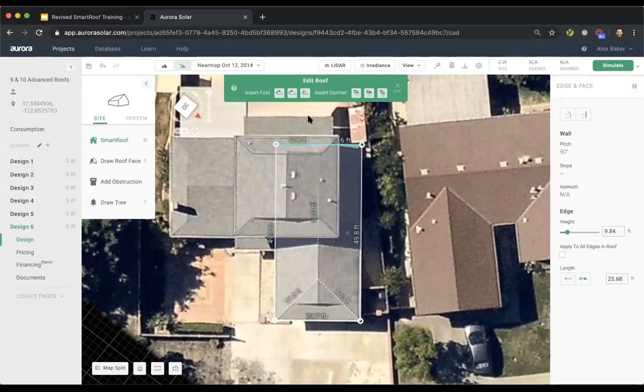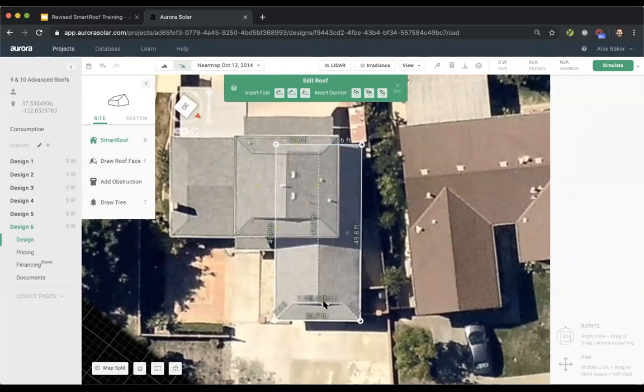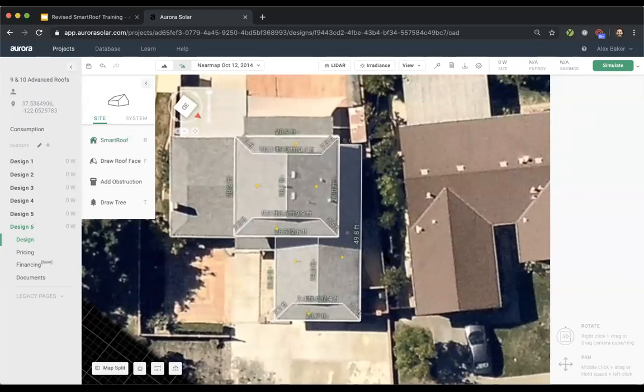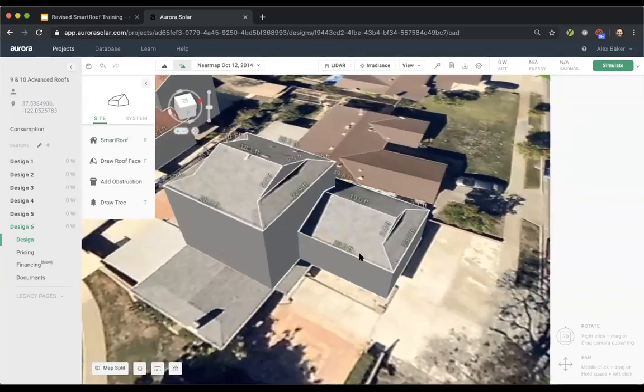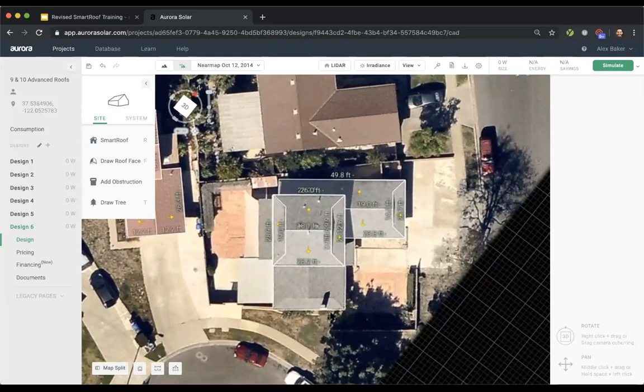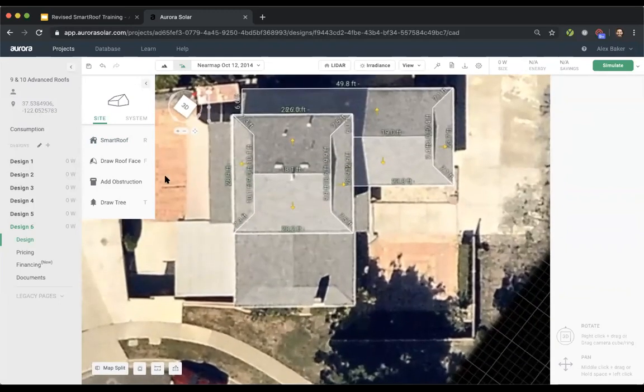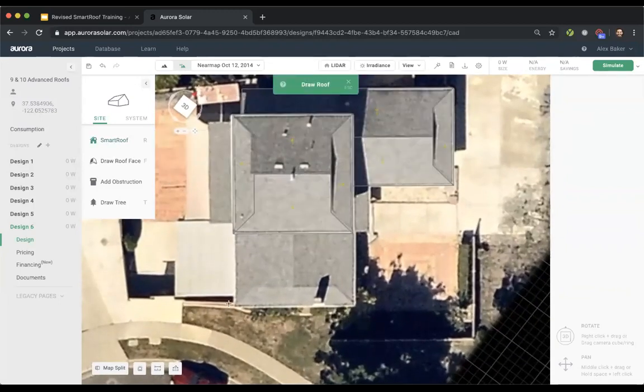And I'll make it gabled on that side, and then we'll add in our vertical fold in the front. And I'll double click and watch how those merge. Looks good so far. Let's do the third piece. This is the most complex piece. So I'm going to select all of the corners here. Because I want this to be a continuous slope, I want to combine this all as one. Now I want these to merge, so I just want to overlap these a little bit.